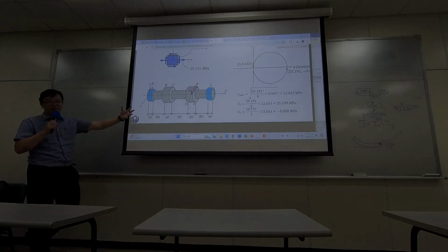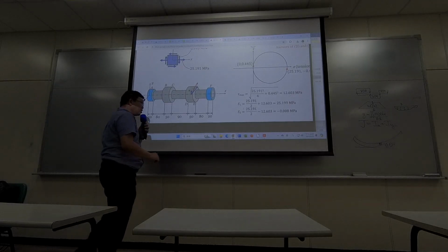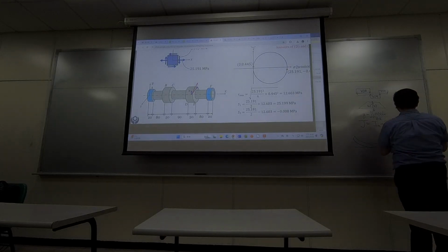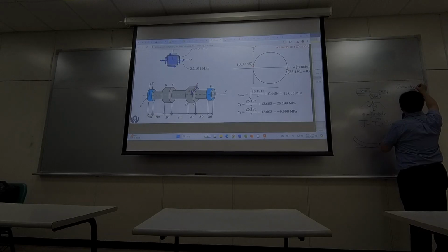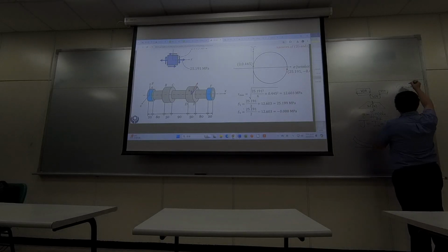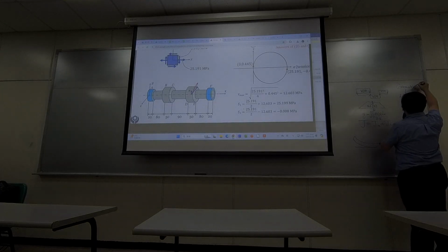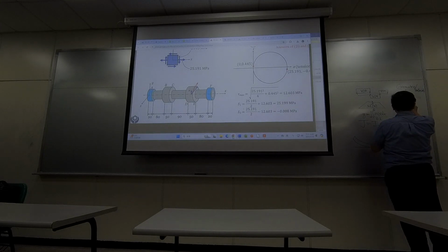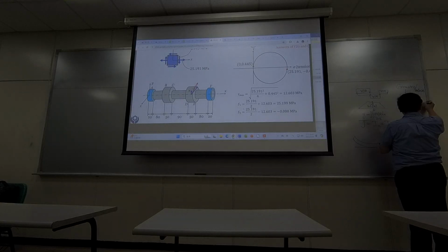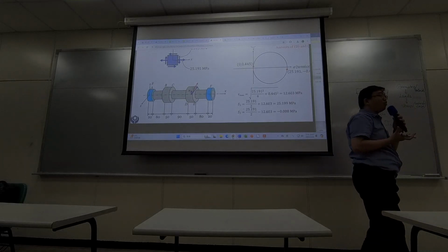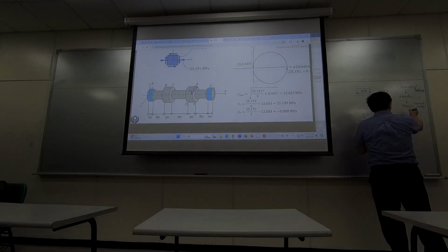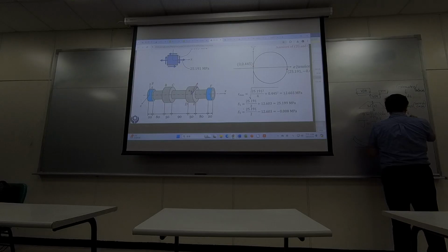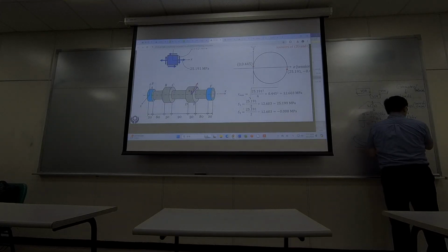So the process of mechanical design now becomes like this. You have a geometry, with materials defined as well. It carries loads, and then you do some analysis to figure out the stress, and you find out which position is carrying the worst, basically the largest, load, so you know where the weakest point is. Then you need to analyze the stress in a proper coordinate. So actually you need to do Mohr circle to figure out what the principal stress is.